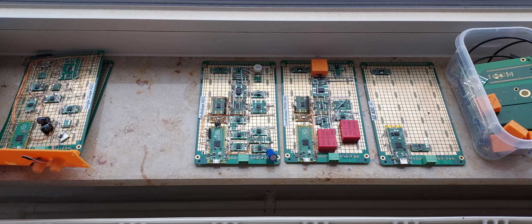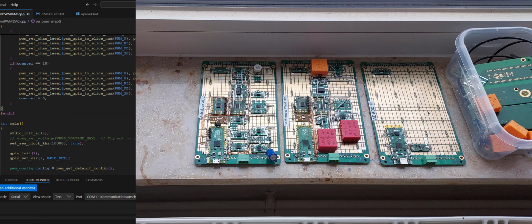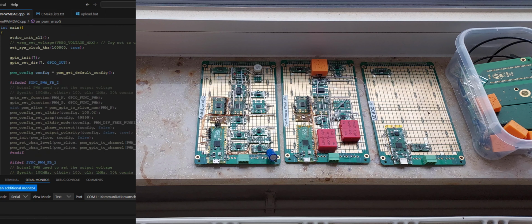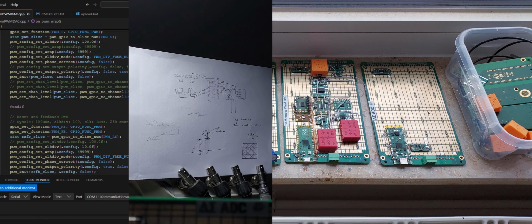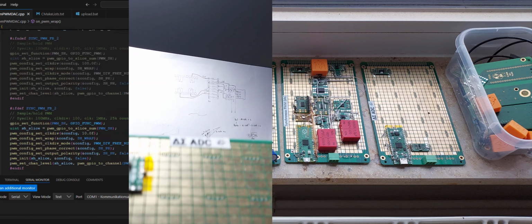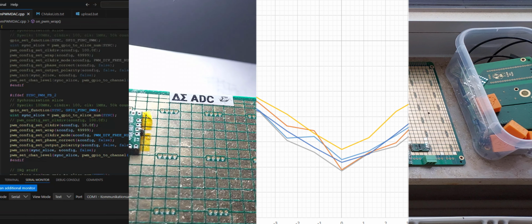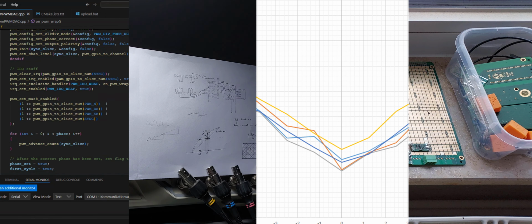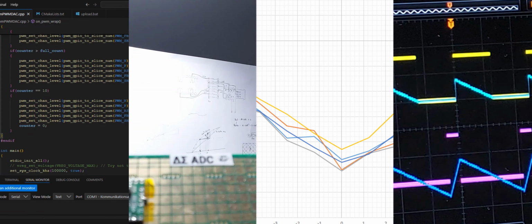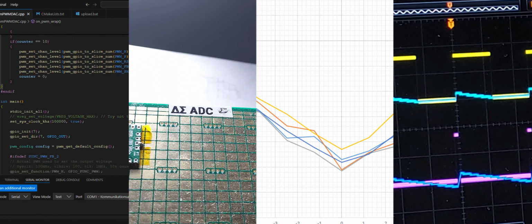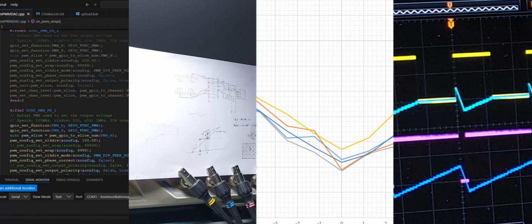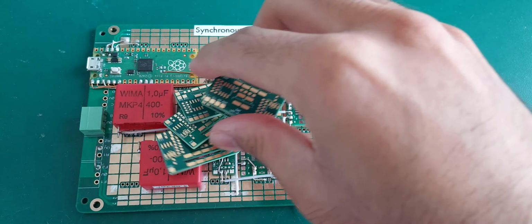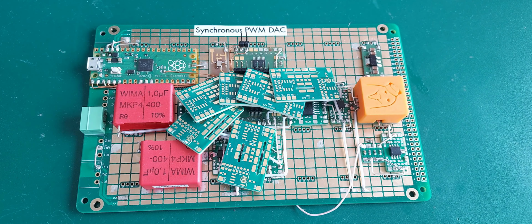It was not entirely a waste of time, however, since I learned quite a few things along the way. Using the RP2040's PWM peripheral and associated interrupts, optimizing the planned layout for the Delta Sigma project, investigating the effect of various PWM methods on INL, and the sectional average integrator also gave me a few ideas for a Delta Sigma control scheme. And regarding PWM DACs, the future still holds possibilities.